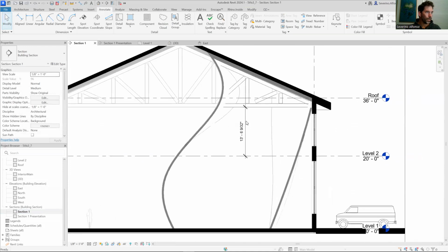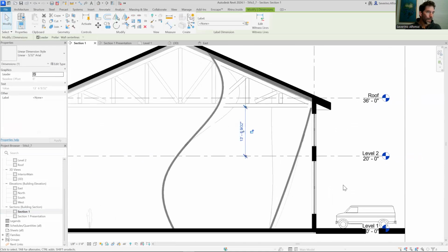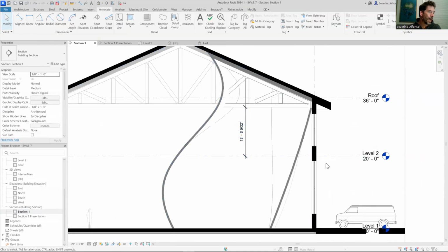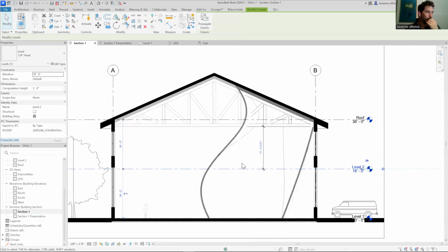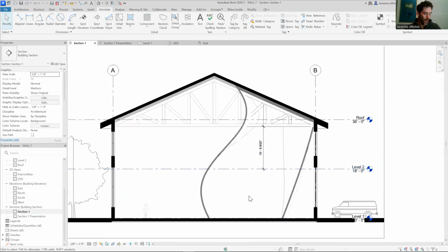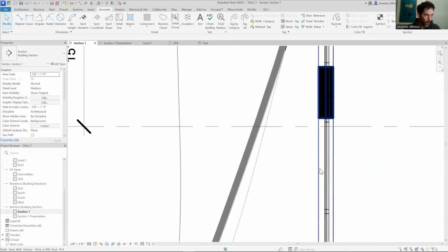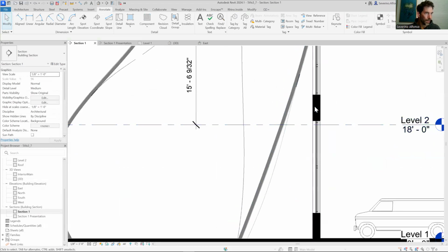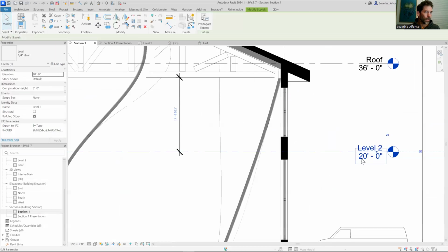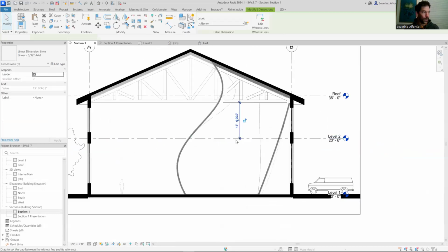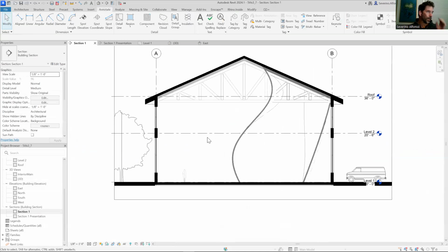That's 13 feet, which is a space that you can definitely inhabit. But you could also take this maybe to 18 feet if you want. It comes down, so you have a generous space. I want to take it up just because I probably want the floor, if it exists, to hit the center area. So I'm going to pick it back and potentially even put in 6 inches higher. So it's 13 feet. That's perfectly fine. I want to delete the dimension because I don't need it.